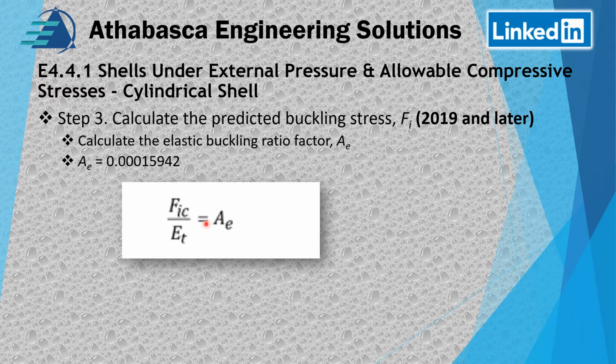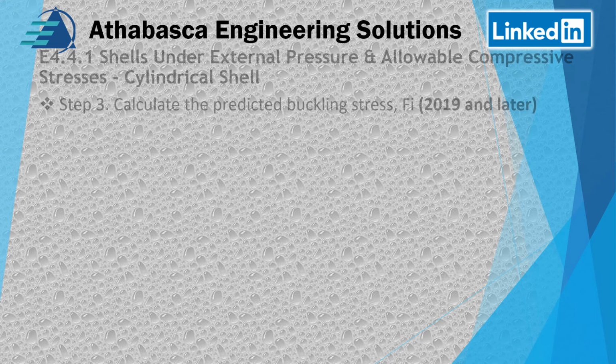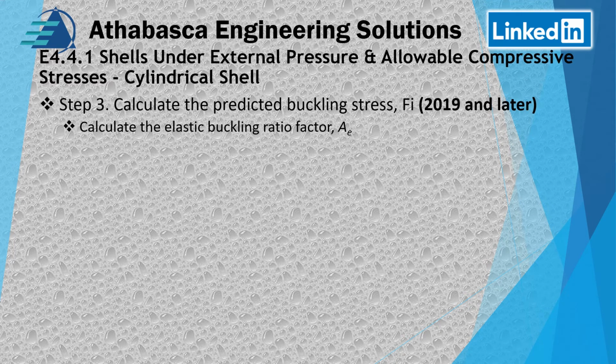And basically, when I did the math, my ratio here was AE over this, and this is the ratio that we start with. And so we continue on with that, and we calculate the predicted buckling stress. So basically, just step 3 that changes. Once we get through step 3 with the later than 2017 version, so if you work in 2021, you're basically just changing one step, which is step 3.